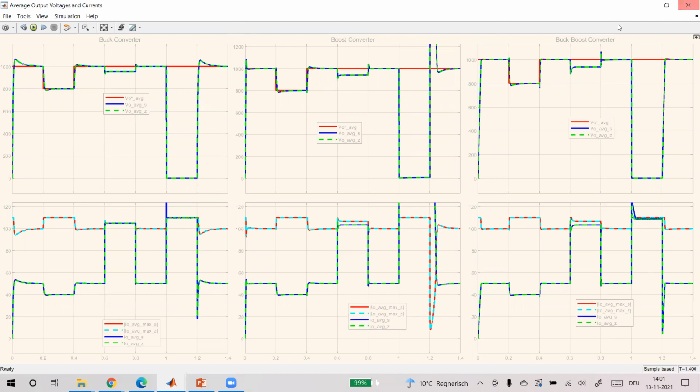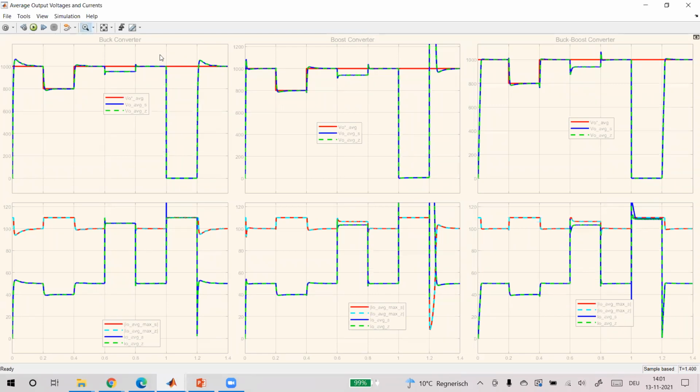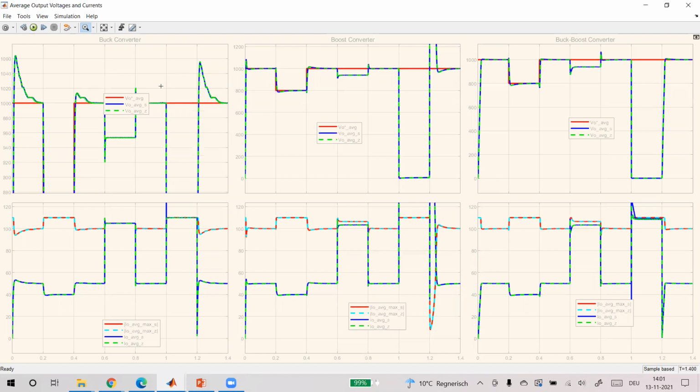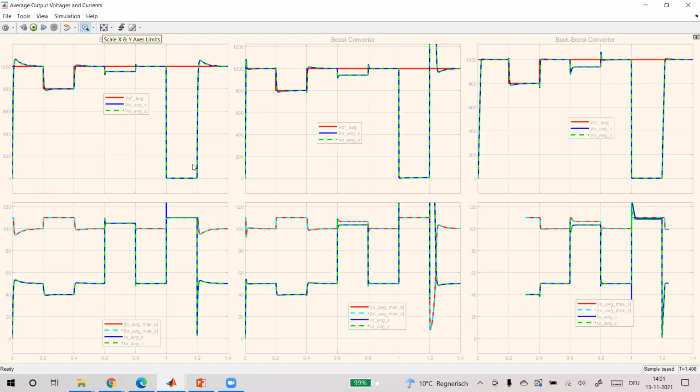And here we have used anti-windup in our system. Before we go further, you can see this result for the buck converter is looking nice. It immediately reacts when the fault or the overload is cleared. You can see during this overload and fault condition, the voltage error is always positive. If you do not do anti-windup, your integrator value will keep on increasing, and then it will not react immediately, and your results would look worse than this.